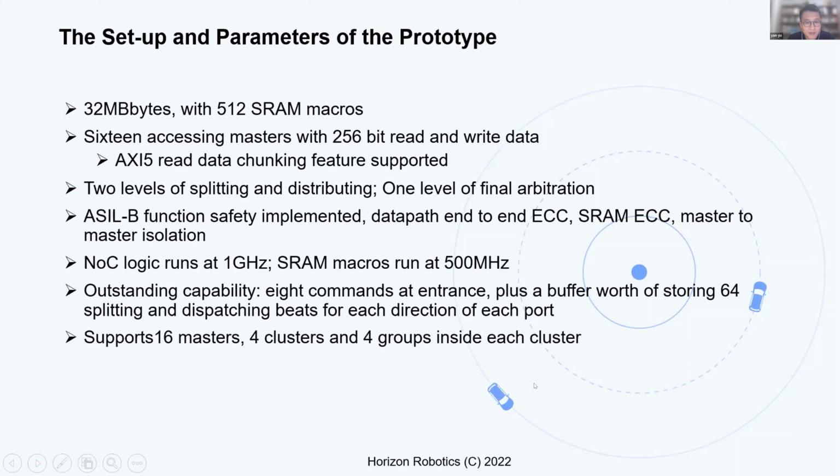As mentioned before, ISO 26262 ASIL-B functional safety is implemented, and to achieve that, we have data path end-to-end ECC and SRAM ECC. So besides the 32 megabytes of functional storage, we also have some storage for the ECC bits. And master-to-master isolation is also implemented.